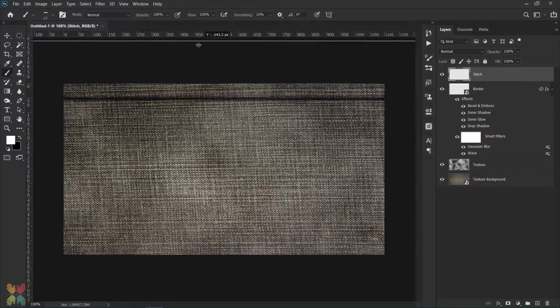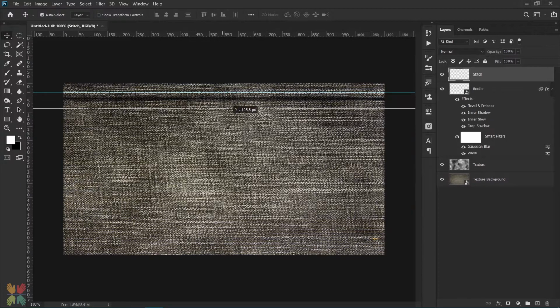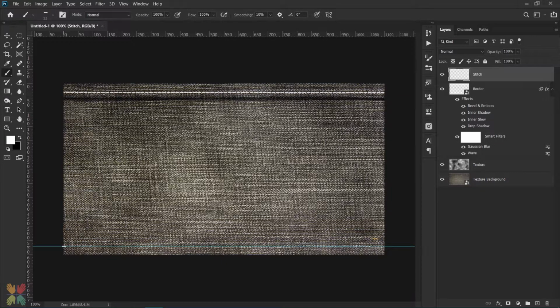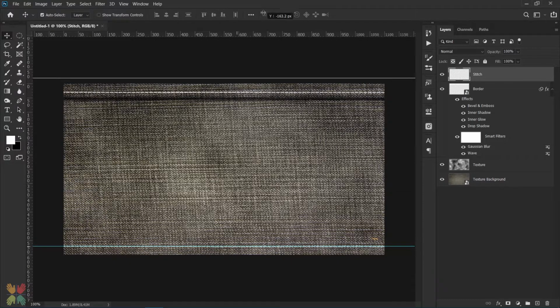For that I'm going to use the scale to bring it down right here. And I'll use my brush. I'll just dab it at one end. Then I'll go to another end and I'll hold my shift on my keyboard. And if I press again, I get a straight line. Pressing V will bring out my move tool and I'll bring this line below. And B for brush, and again I'll do the same thing right here. I'll hold my shift to make a straight line. After that I can remove this line.